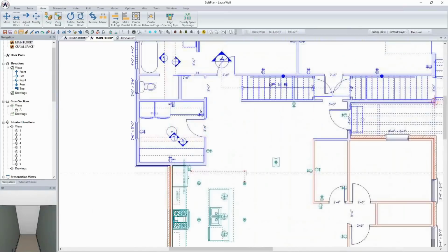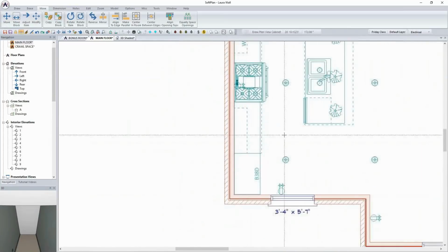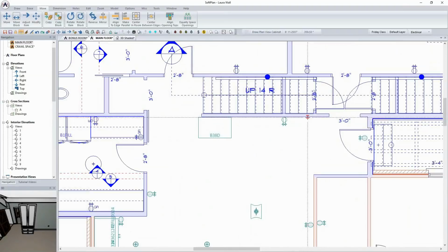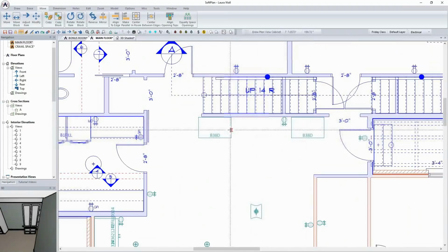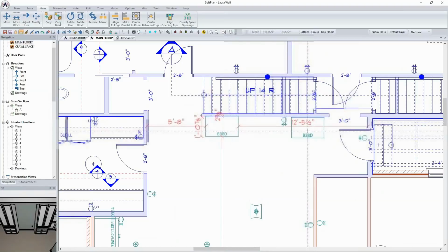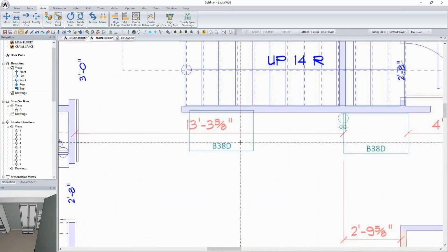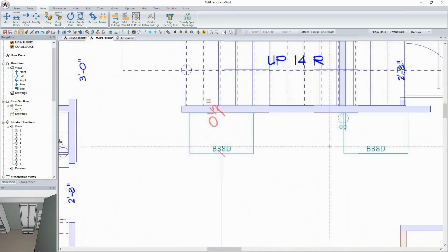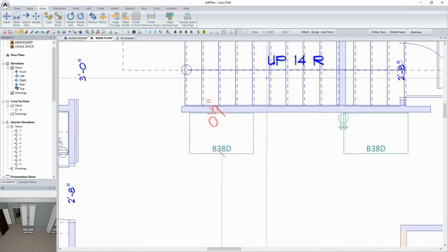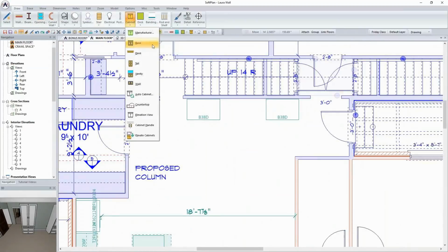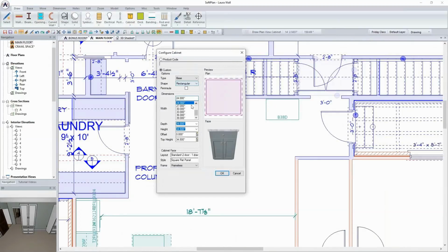And so at this stage now, using the draw select, this is where I could come in and select the cabinet that I've already custom created, and basically I'm just going to add a couple of these on either side. So we're just going to do this, and I'm going to finish this by creating, if you will, a coffee bar situation that will be used in here. So I'll just come in through draw, and I'm going to do this actually inside the drawing mode. So draw through and then cabinet, and select the base option.